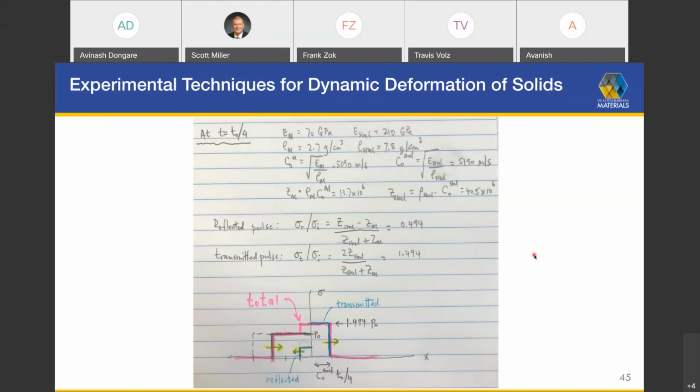The wave speed strictly is independent of the magnitude of the stress or the direction of stress, whether it's tensile or compressive, provided the material remains linear elastic. And these two are completely decoupled. If you were to yield the aluminum, the behavior would be more complicated.